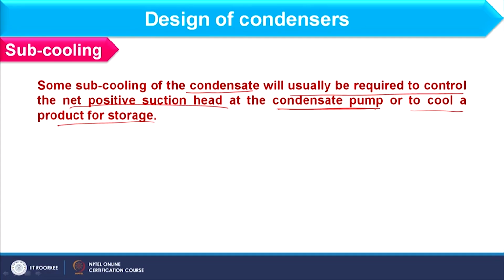So, here you can observe that some subcooling we do intentionally, because after that we have to pump this condensate to the storage tank or some other equipment, and for that purpose we need a pump. Okay. So, a pump cannot be operated if I am not ensuring that the feed is entirely liquid. So, to ensure that, some subcooling should be there.